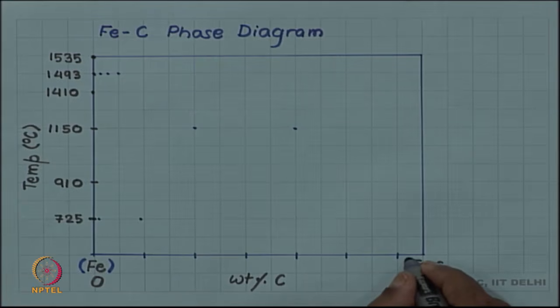We stop, as all traditional iron carbon phase diagrams stop, at Fe3C which is an intermetallic compound and its weight percentage is 6.67. If you think of its atom percent, you can see there is one carbon atom out of 4 atoms.